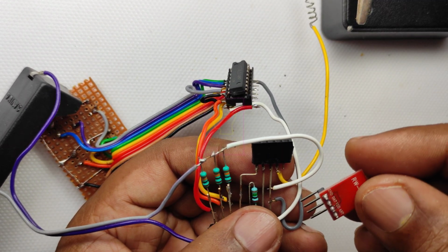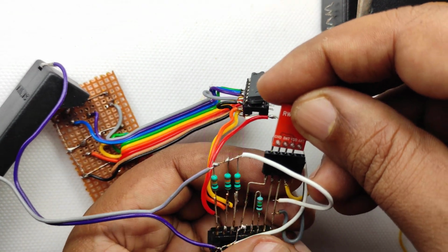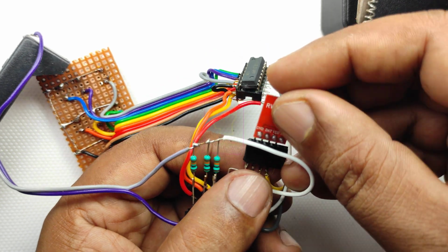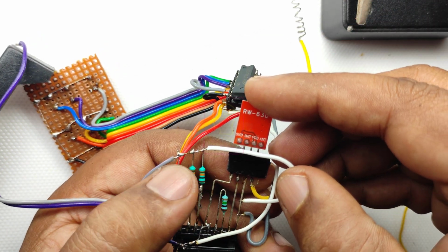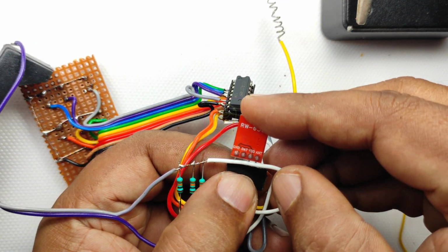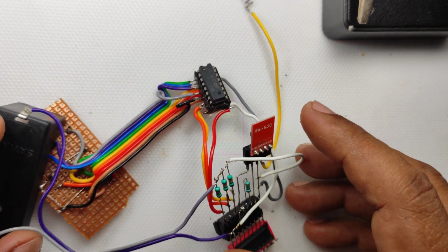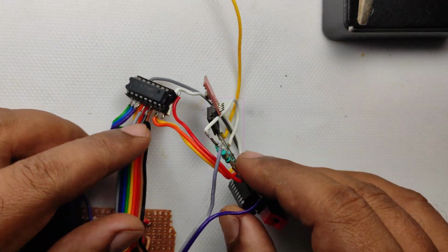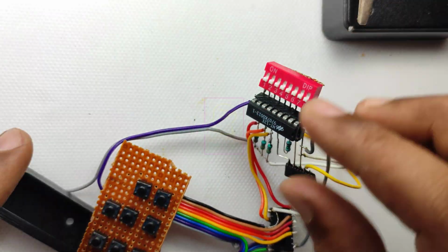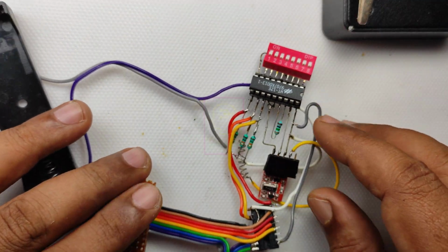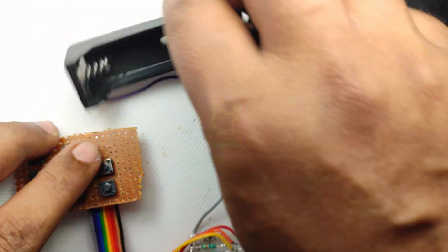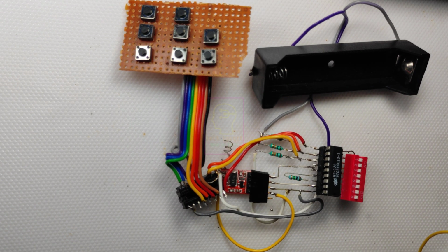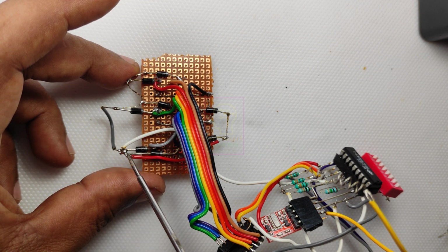While designing the circuit, I made one mistake. We are using a 3 to 8 bit decoder and the output of 1 bit will be high every time. We cannot control that input bit, which is the truth table entry of 000. With that, we can effectively control 7 devices only. In order to fix that and to control 8 devices, we need to make use of the enable pin of the 3 to 8 line decoder, that is 74138.